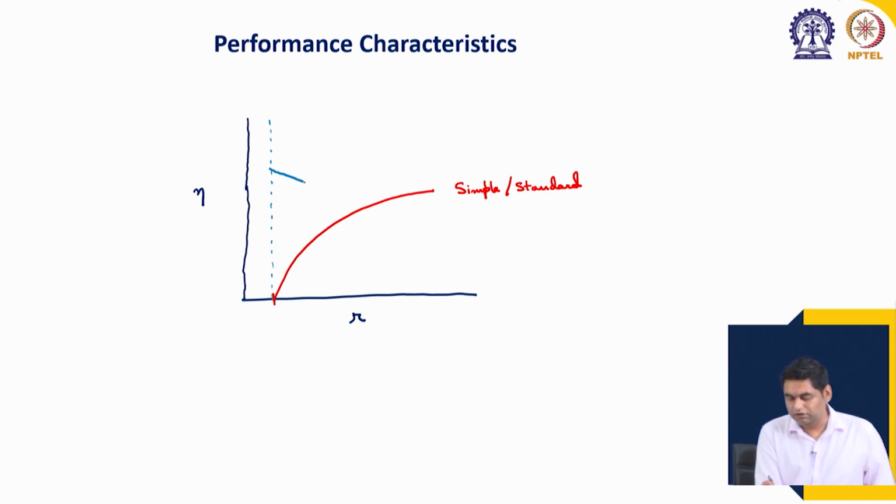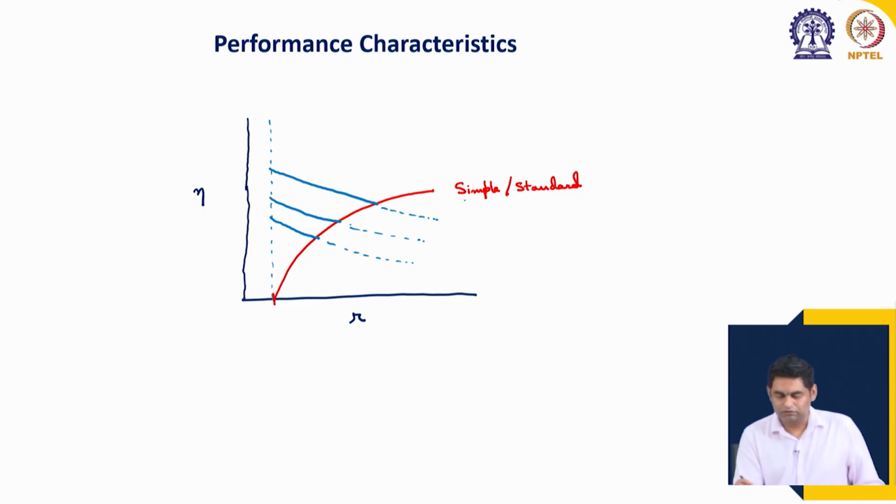So, the efficiency decreases and at some point it goes below that of the simple Brayton cycle. Okay. So, this is for regeneration, and we have seen what should be the crossover point for this case, which is when the compressor outlet temperature is equal to the turbine exhaust temperature.